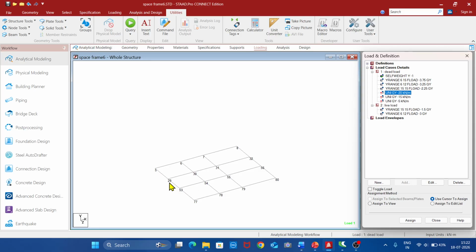So here we will be having the plan. So having the plan in hand, we can apply this wall load wherever wall comes. Say if I have walls here acting over this plinth beam, this plinth beam, this plinth beam. Outer will definitely be having walls, because we'll be having walls on the periphery necessarily or compulsorily, and inner walls have to be applied depending upon the plan. Say if I don't have a wall here, then I can skip that. I can add only here.